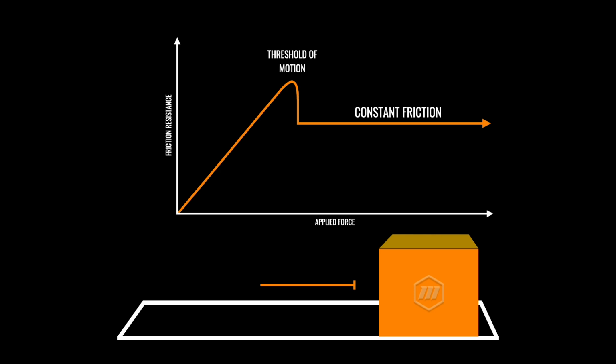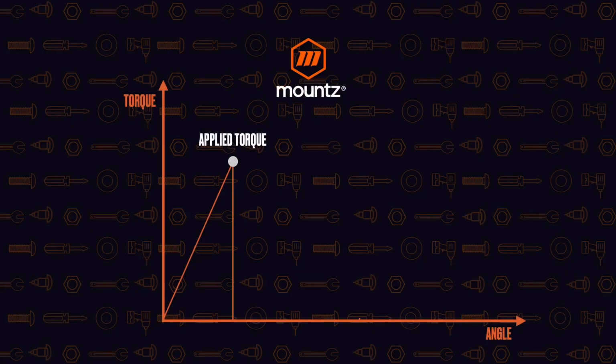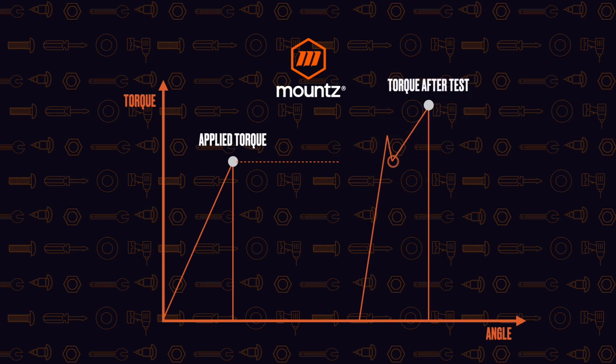And so that's what we're looking at when we add additional torque to that fastener, or additional movement. We may see a rise in the torque, then it dips back down, and then it keeps going as we apply more angle to that fastener. So at about 3 to 5 to 10 degrees or so is typically where you can see what the value was when the tool was applied, or when the torque was applied.